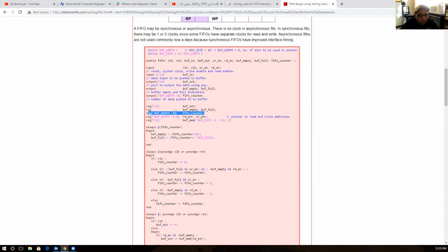Somebody will tell me, oh, but you said it's going to be 16 - 1 to 0. No, in a FIFO we will have an extra one for the final reporting, and I'm going to show it to you. But the pointers are the pointers, those are two different things. We are defining them now. They do not exist in the in and out, they're going to be internal.